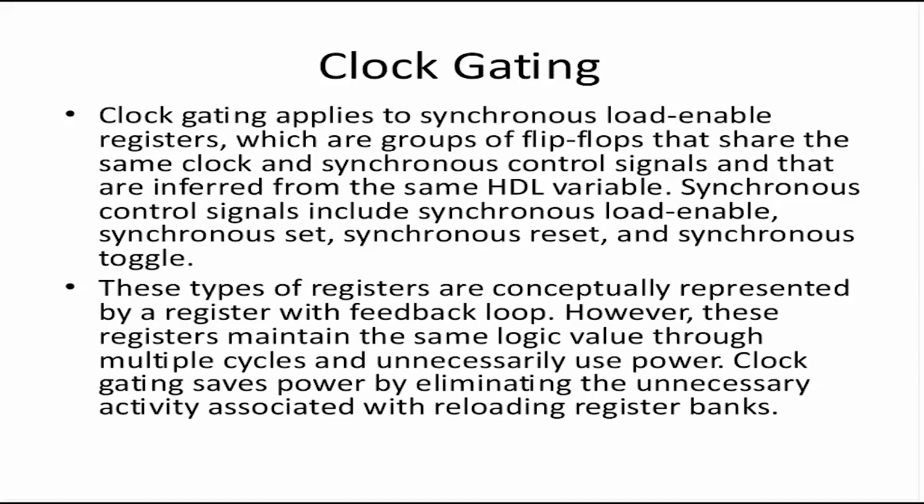So clock gating is, I would say, the most popular RTL or gate level power optimization technique. Clock gating applies to synchronous load enable registers, which are the group of flip flops that share the same clock. So we are talking about a type of circuit which is very popular. It's called shift register type of circuit. Your design will have a number of shift registers which share the same clock